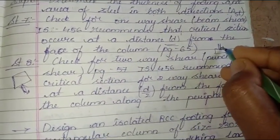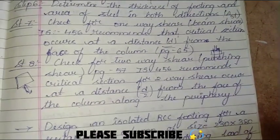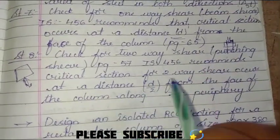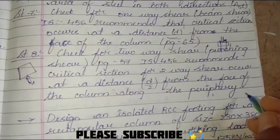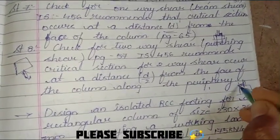So from the face of the column, we are considering it as D. This would be the one-way shear, the critical section for the one-way shear. And for the two-way shear, it is at a distance D by 2 from the face of column along the periphery. See, periphery from the edges. So from the edges, we will just be leaving the distance D by 2 from the column.